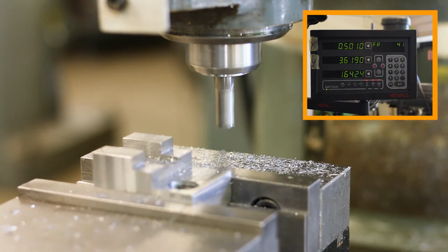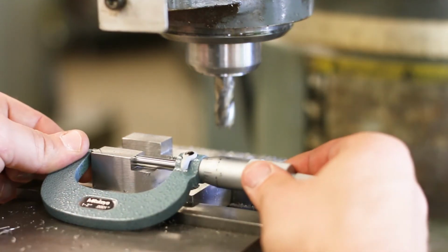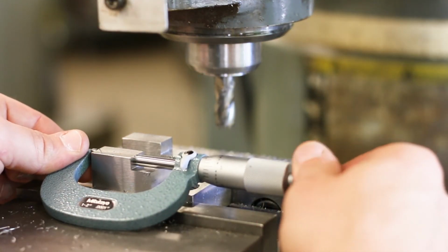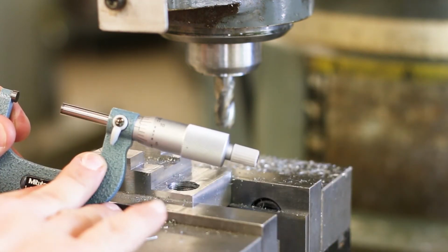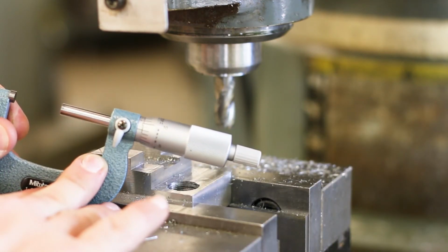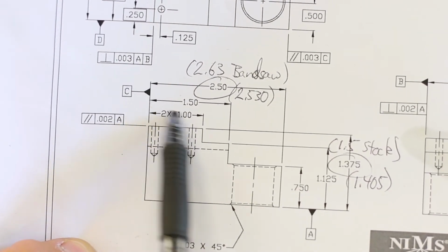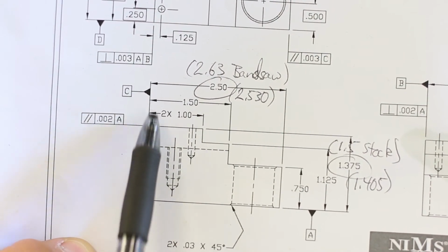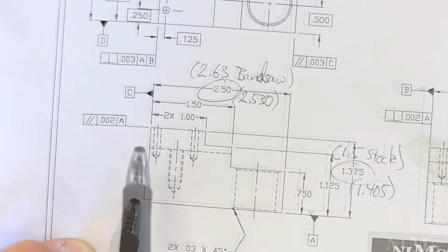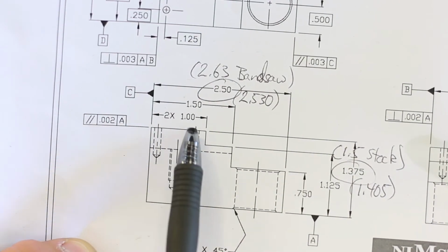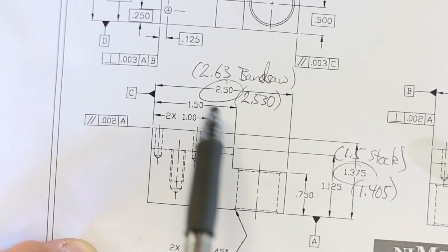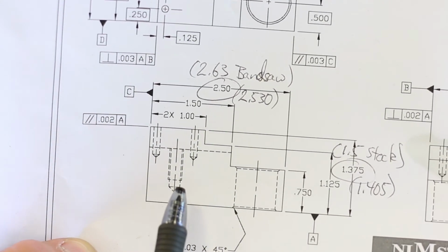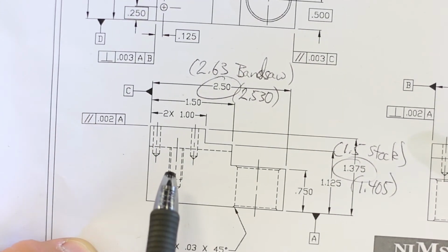Okay, let's take a measurement. So that says 1 inch and 8 thousandths. So the final dimension in this direction is 1 inch from datum feature C. So if we're at 1 inch and 8 thousandths, then we have to take 8 thousandths. Now that doesn't really agree with what the digital readout was telling us, but the micrometer doesn't lie, so we'll